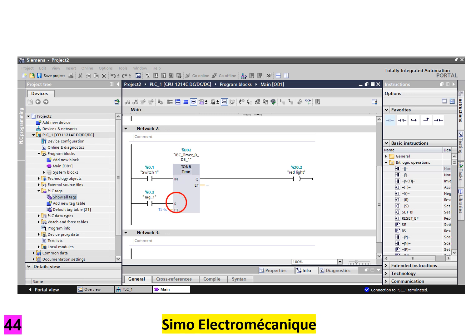In addition, it has a reset input R, which resets the timer when triggered. Note that the timer can be reset even during timing. Here, the TONR timer is set to time for 4 seconds. After 4 seconds of input IN being on, output Q is triggered. Reset is triggered here by a switch on input 2.